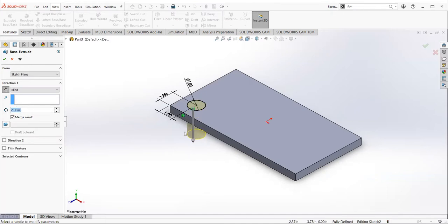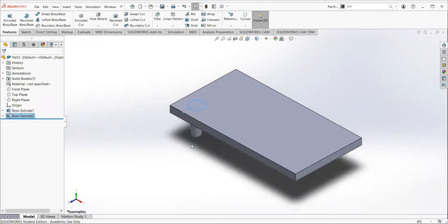It seems to be still linear, so we want to add an angular extrusion. Click on the conic, it's kind of a pyramid, then change into the right angle. In here we want it to be 7 degrees. So click on yes. So we have added the first test holder.